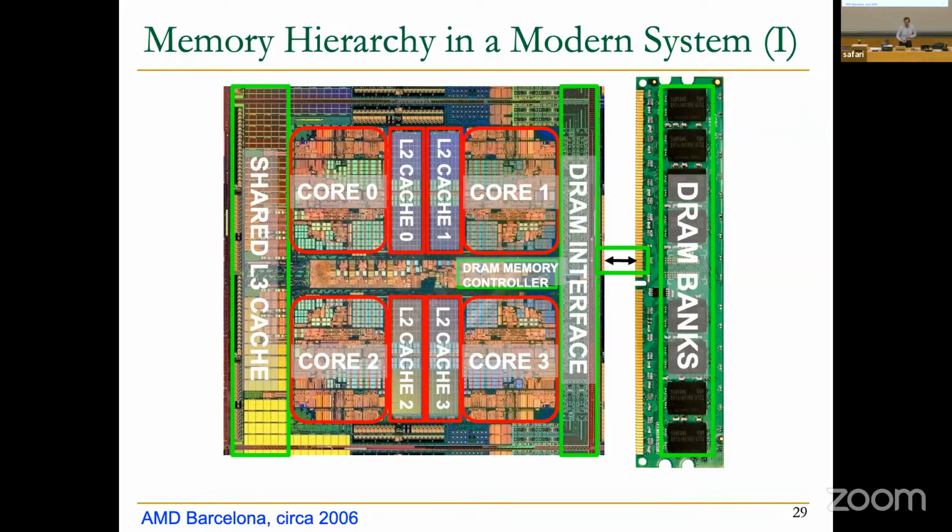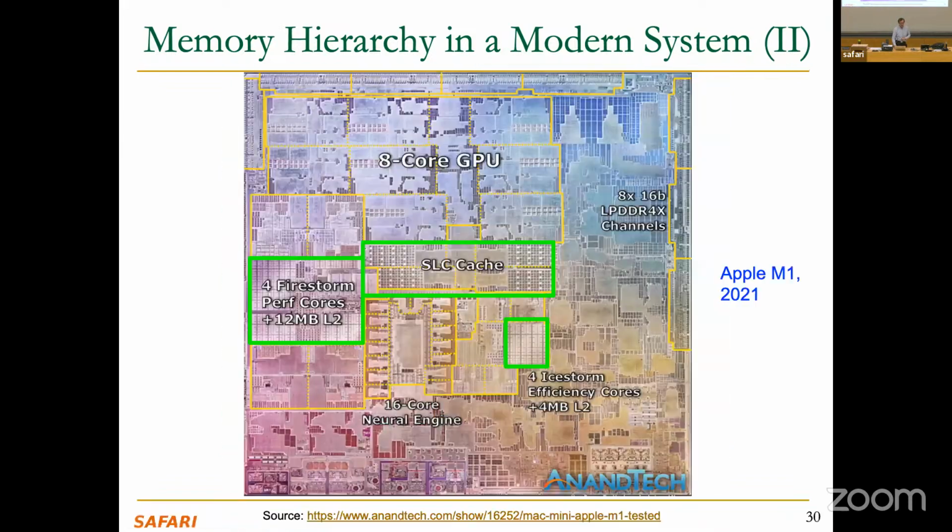So these pictures I've shown you, basically today's systems have memory hierarchies, right? Cores have registers and then L1 caches, and then you have some L2 caches, and then you have some L3 caches, and then you have some DRAM, right? And there are controllers for all of these. We will see some cache controllers today and tomorrow. And you can see that some of these are explicitly described. Some of these are not explicitly shown in this, but there are caches in the cores. There are L2 caches over here. A lot of the regular structures are essentially caches on a chip. And Apple has a system level cache. That's essentially another cache shared by these different cores and accelerators.